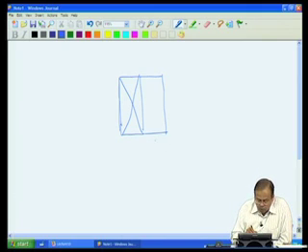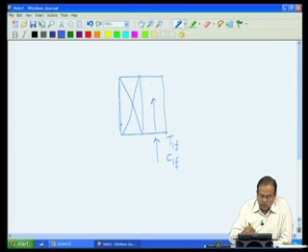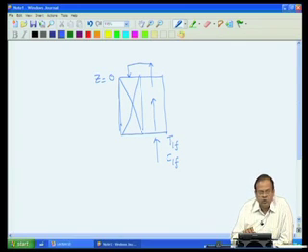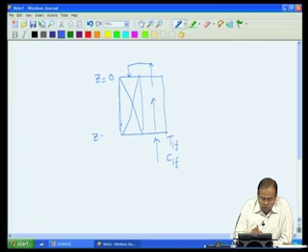So, I have my reactants at temperature T1F and concentration C1F, which are going to flow through this empty shell before it enters the reactor. Keeping in mind that our reactor inlet we always put at axial position 0, let us put that as 0 and let us say my catalyst bed is of length L.